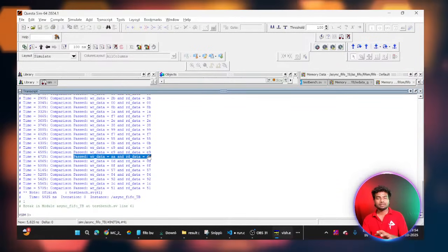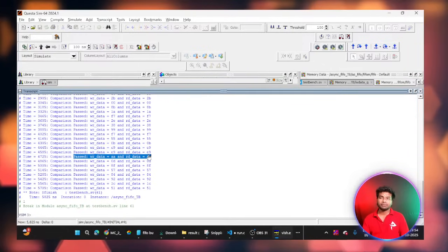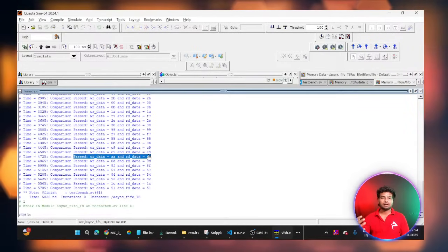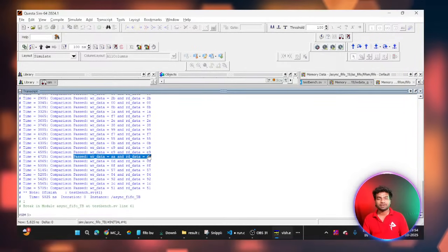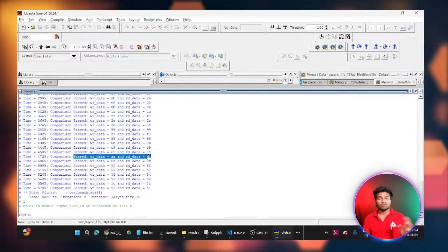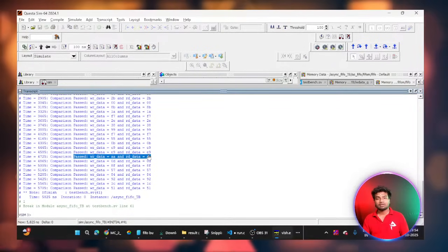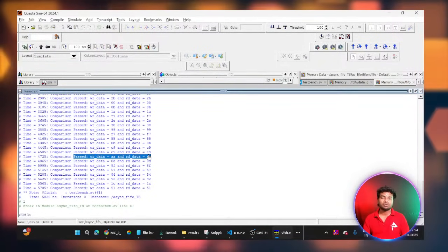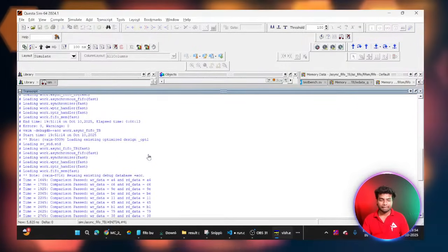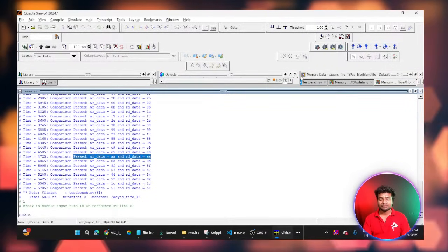This is only a simple circuit, a simple design. When entering big topics like big chip-level SoCs, the FIFO size is different and the FIFO working is also very different. There are a lot of handshaking signals in the FIFO, like FIFO overloading and non-overloading. There are a lot of control signals when entering many different clock domains and a big FIFO buffer. This is how it works, and this is how we can check the FIFO buffer with two clock domains.